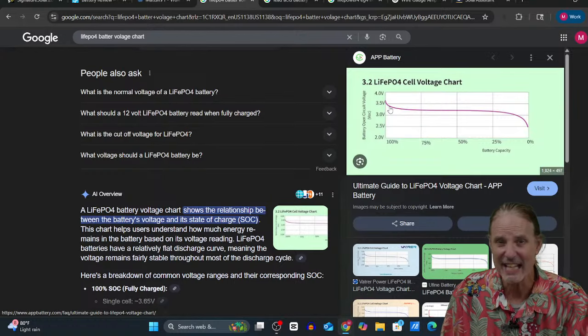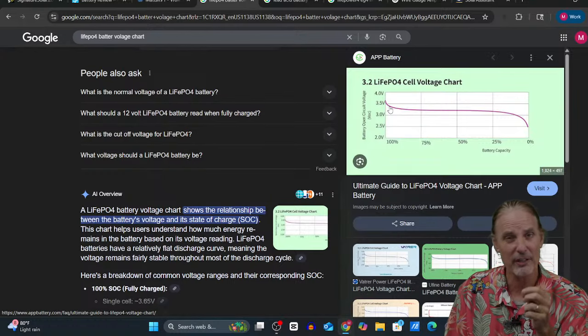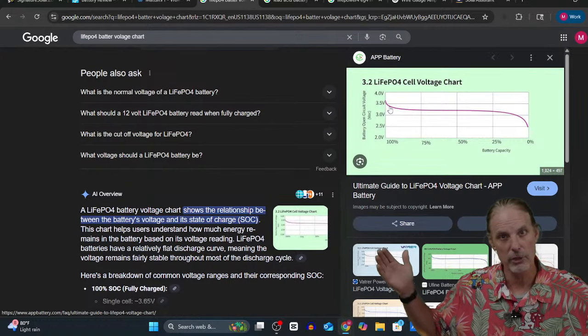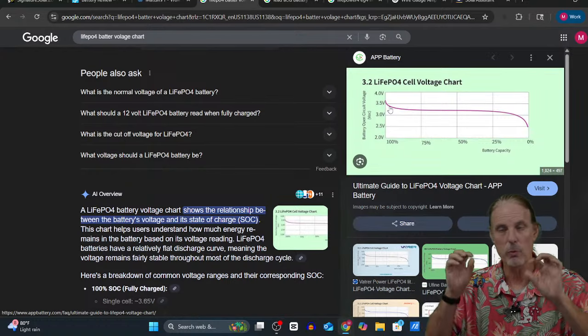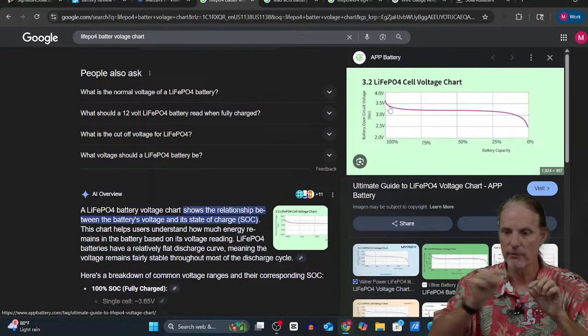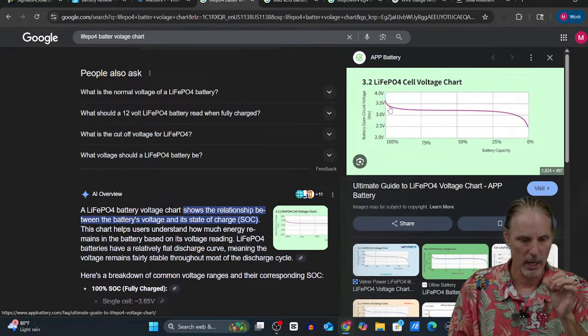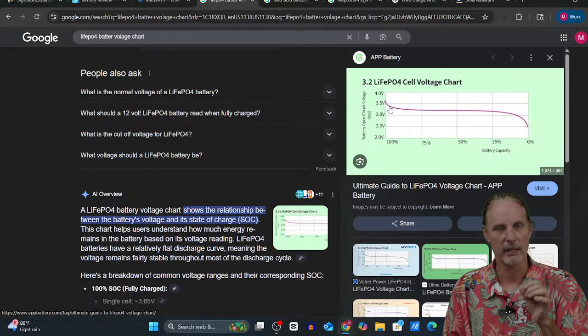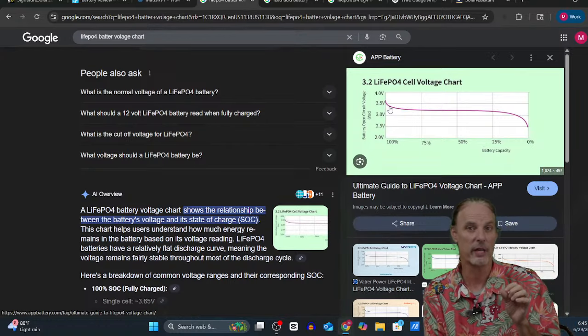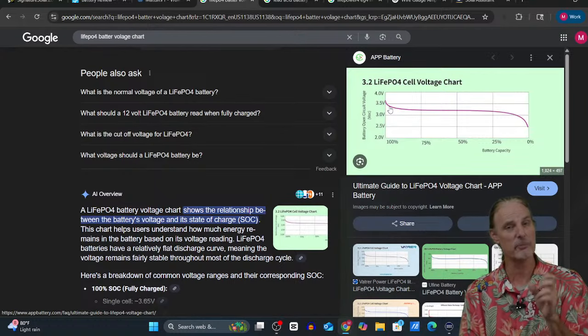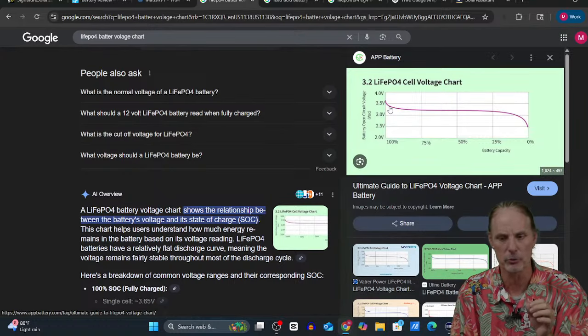If it's instantaneous, there's also a very good likelihood that not all of your connections are perfect. What you want to do is check the voltage at different places. This is one thing that I did last week with a system that I set up, and you would be surprised how good of a debugging tool this is.